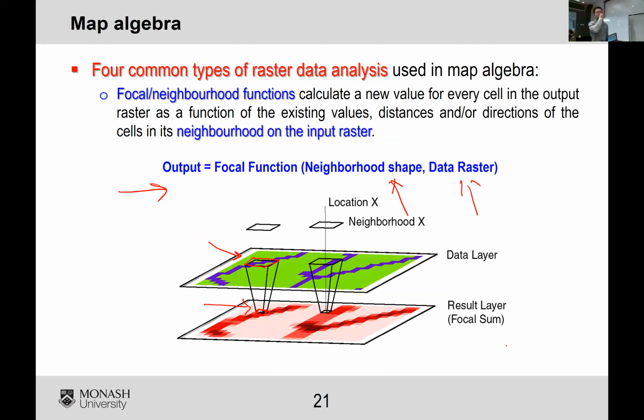And just one application of this, if you have an elevation raster, a raster representing the elevation of a terrain, the data is very rough, so you want to smooth the surface. So this is the method you can use, right? So you're taking an average of an area and assign the average elevation to that cell. So eventually you will get a smoother terrain or smoother elevation output in your output raster.